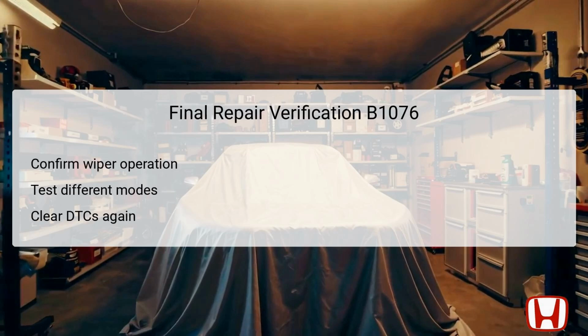The final repair verification step is essential to ensure that the windshield wipers are functioning as intended after any repairs or replacements made. Start by testing the wipers in all modes, intermittent, low, and high, to confirm that they respond accurately to the switch adjustments. After verifying functionality, use the HDS one more time to clear the DTCs, effectively resetting the system.